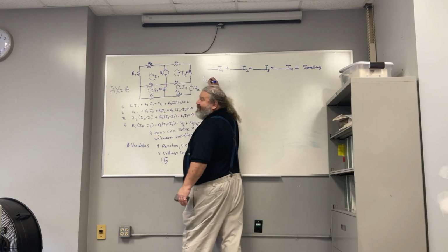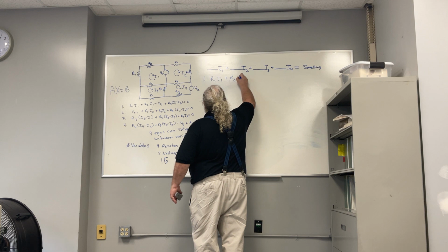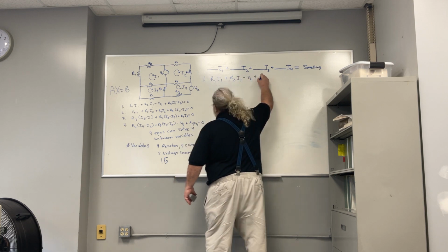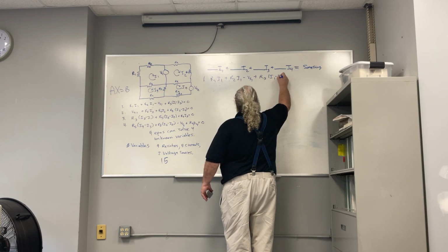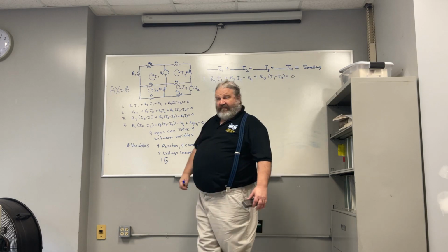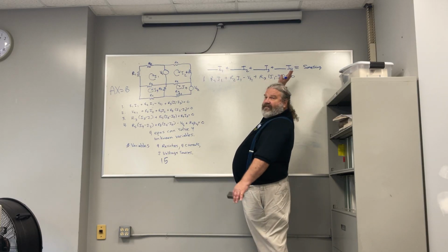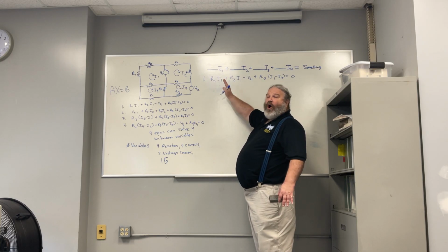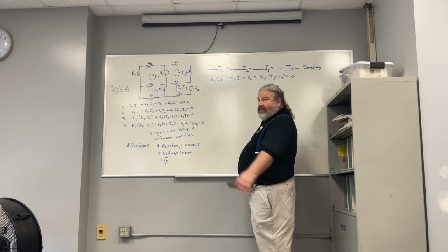Okay, so Quinlan, the first equation here is R1I1, R2 times (I1 minus I2) minus VS1 plus R3 times (I1 minus I3) equals 0. All right, so Quinlan, we're going to go left to right, and we're going to follow this exactly. So the first variable that I'm trying to find is all the coefficients for I1. So which ones have I1?